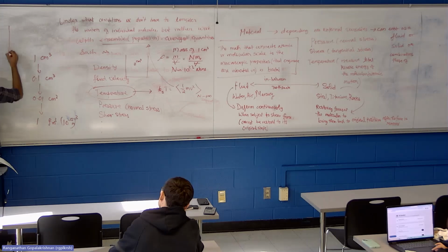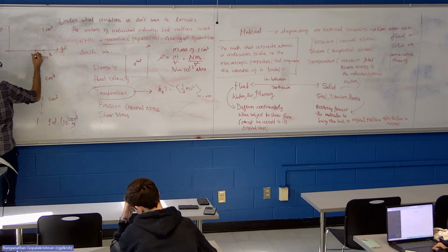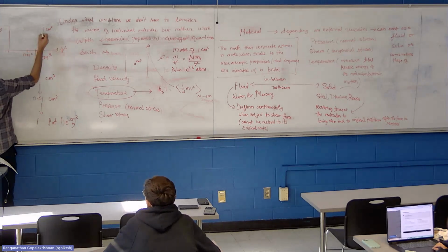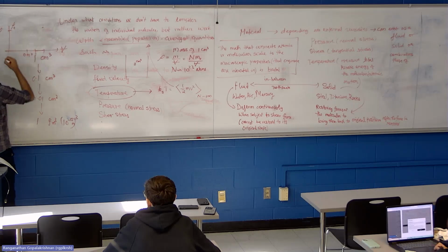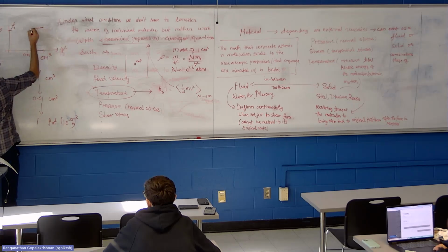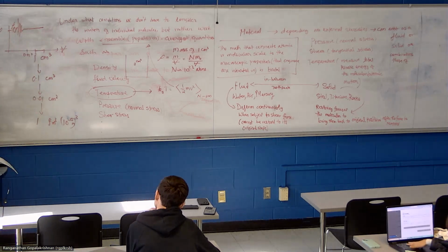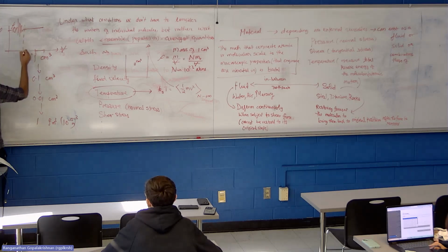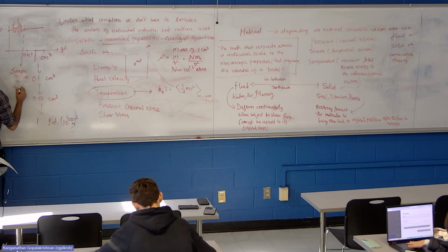Or in other words, if you measure density with sample volumes, you start at, let's say, 1 centimeter cube. You make it 10x smaller, 0.1. You make it 100x smaller, 0.01. You are going to measure some density here. I'll call it rho naught. This rho naught will stay the same, but at some point, it'll start becoming unreliable as your sample volume becomes too small.